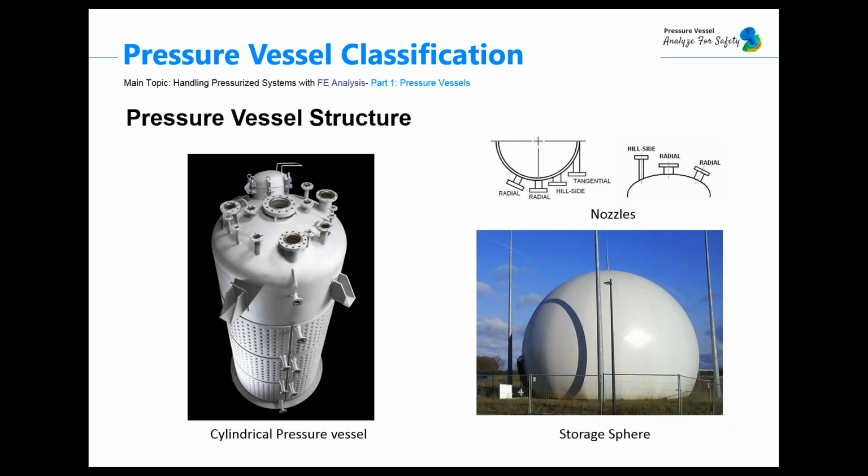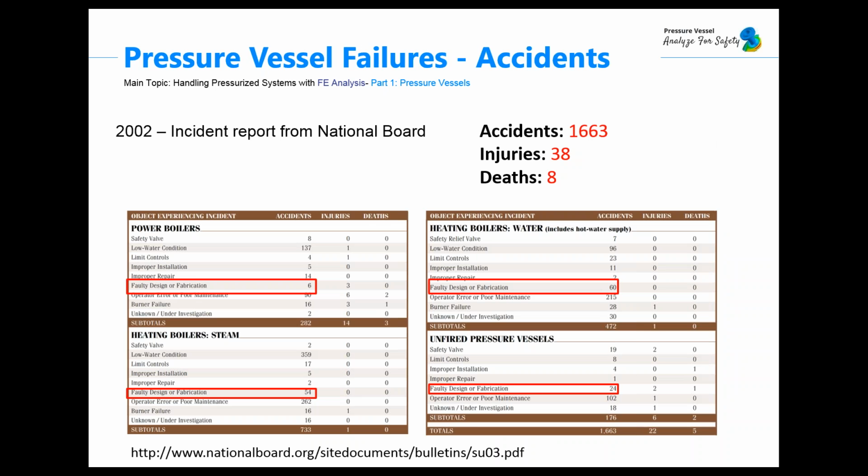Unfortunately, these openings also result in penetrations of the pressure restraining boundary, and as such are seen as discontinuities. This is a term that will appear many times in your practical design procedures. Discontinuities weaken the pressure vessel strength because they are simply sources of stress concentrations. This is very important to know. So let's take a look at the next slide.